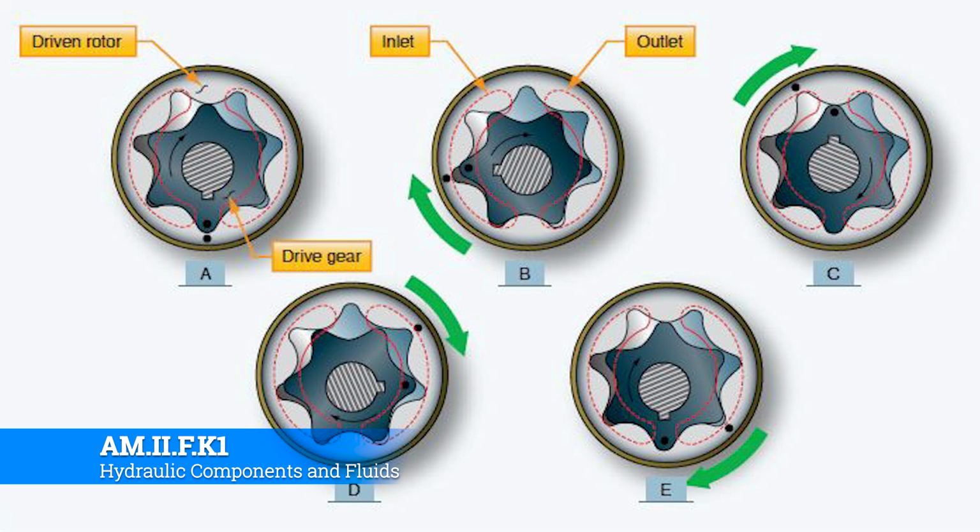One gear will create a pressure cavity and shove it behind a crescent. That crescent will then travel around to the inlet and release that pressure cavity into the inlet. And it's doing it really, really fast. Technically, there's a rhythmic release of pressurized fluid, but it's happening so fast it's basically one solid stream, unless you have a high-speed camera and can slow it way down.